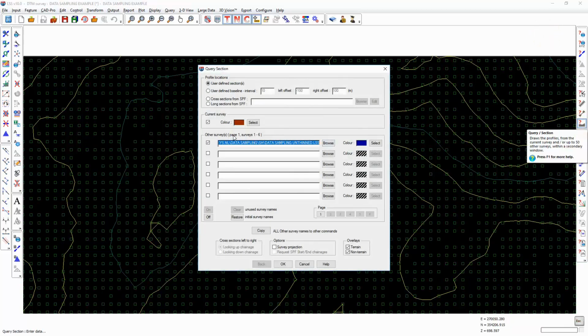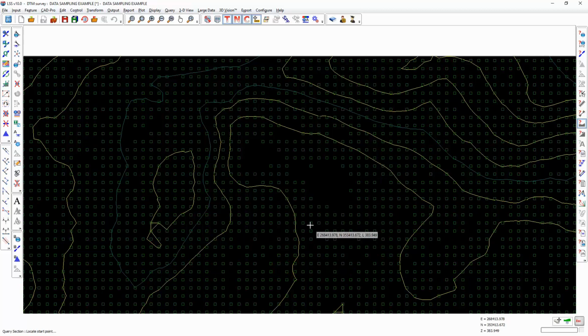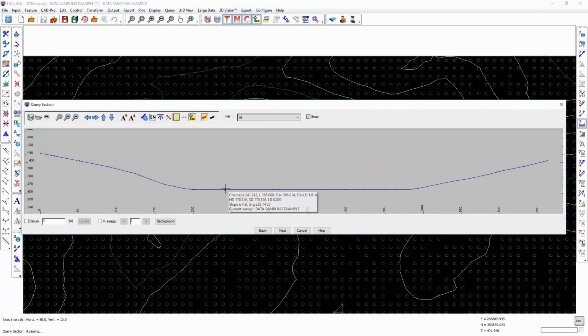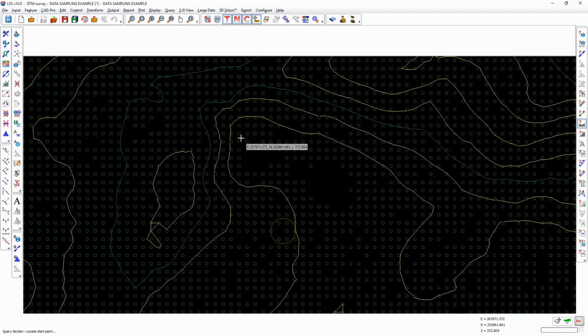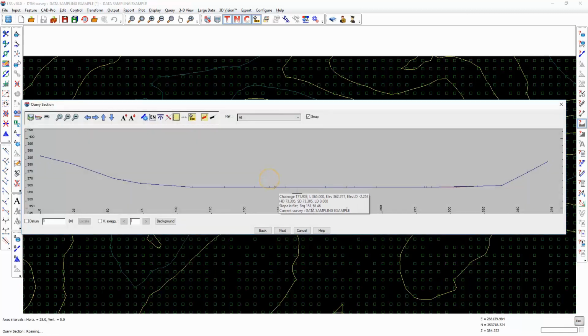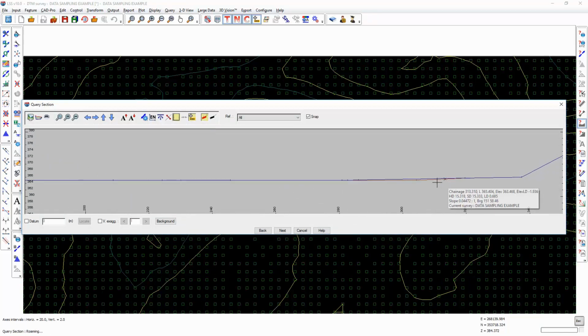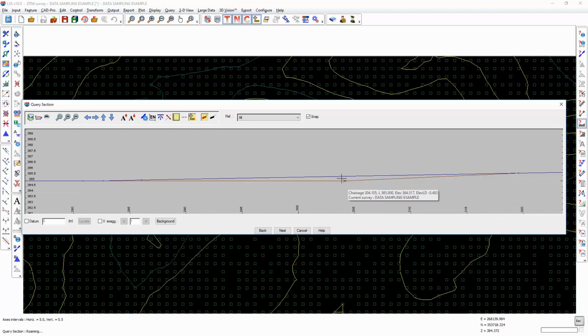And if we were to draw a section through the thinned model and also the unthinned model, through these areas where there are now points missing, we will see that there is no difference in the DTM, or where there is a difference, it will be a minor difference which will equal the tolerance that we have previously defined.